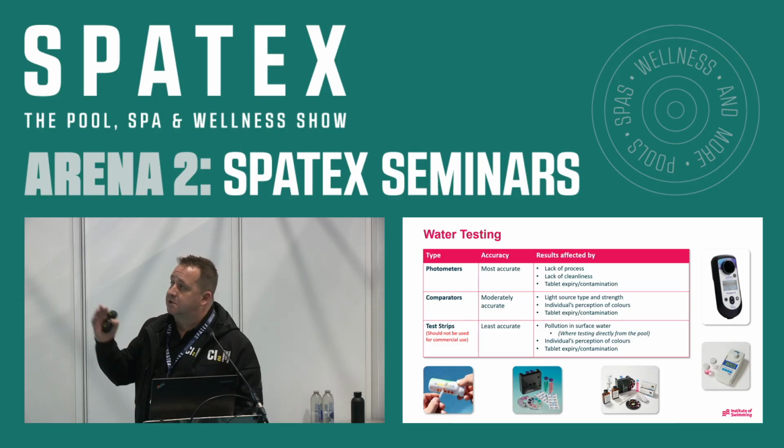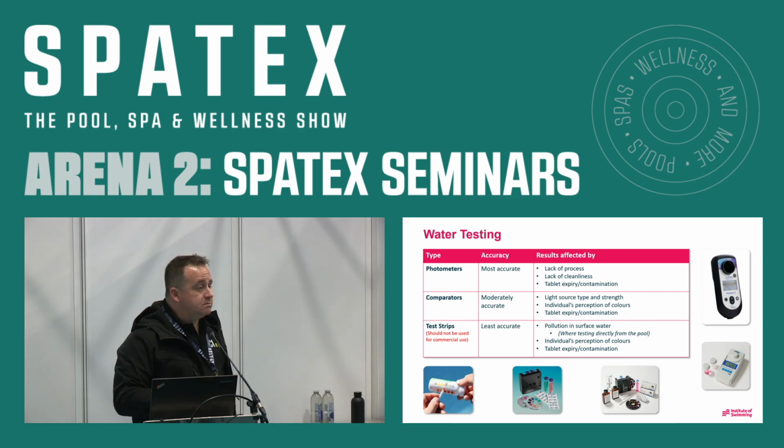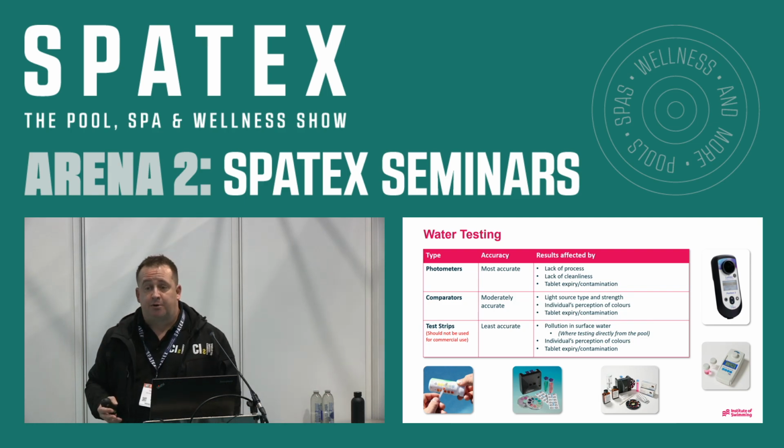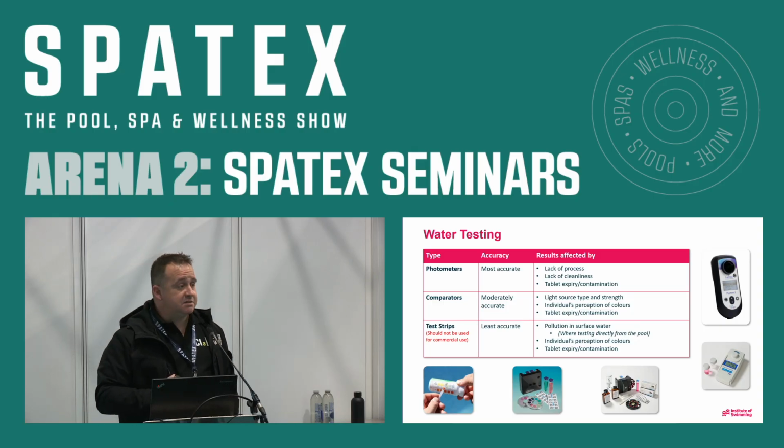When we start looking at water testing, there are 3 main types of testing equipment we can have. Okay, the photometers, the comparators, and of course the test strips. All right, the photometers are the most accurate. Okay, they are affected by lack of process, i.e. you not knowing how the system works. Okay, definitely affected by cleanliness, massively.